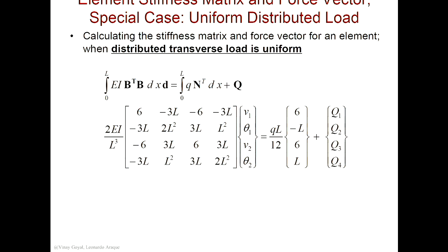This goes with that node. That makes sense. That's the transverse load that has to be supported. So what is the distributed load? Uniform load? Q, right? What is the length? L. Q times L is the total force acting downwards. So it has to be supported by QL over 2 here and QL over 2 here. It came automatically. Okay. We can also discuss the moment, although it takes a little more work.